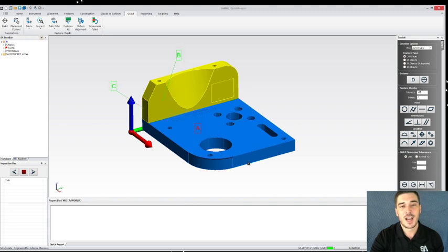Okay, so it's also possible to drag these annotations once you've created them. You can drag them so that they're shown in a way that makes a little bit more sense to you, or that it's not on top of your part. And you just do that by hitting this placement control button in the menu. And once you do that, you can move them around till you get something that you like, and then you can hit save all, and it'll save those annotations.